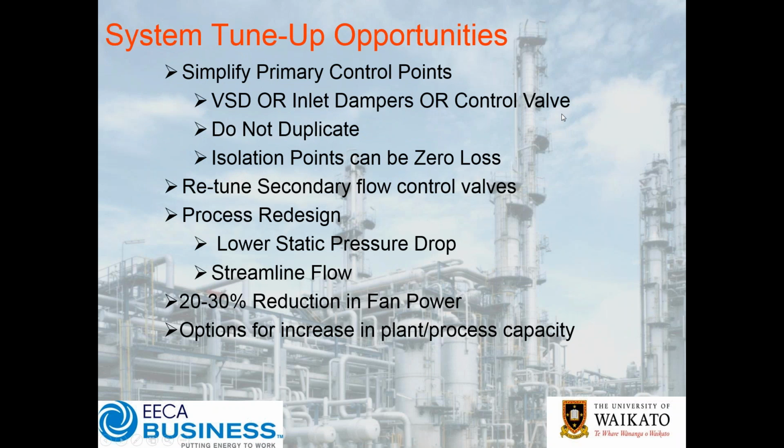So when we look at tuning up these systems, the things to look for: can I simplify my primary control points? Have we got a VSD or an inlet damper or a control valve? We do not want to duplicate. And just a reminder on this point, we see this over and over again where damper valves are installed on a basis of we need to isolate the system for this or for that and so on.